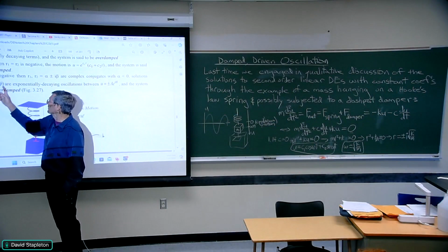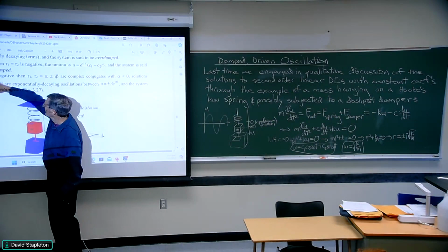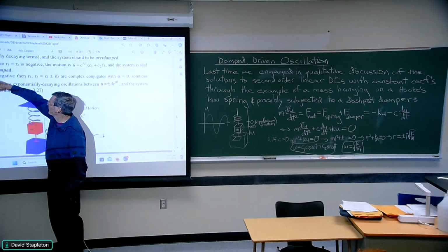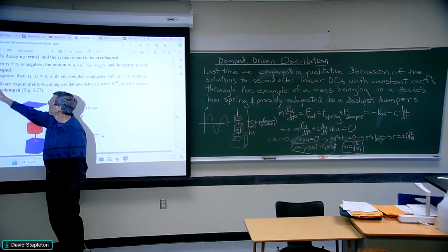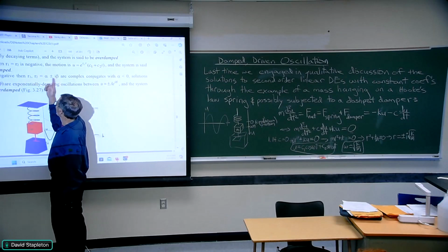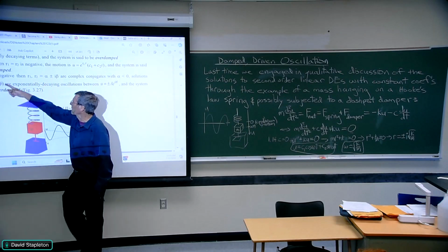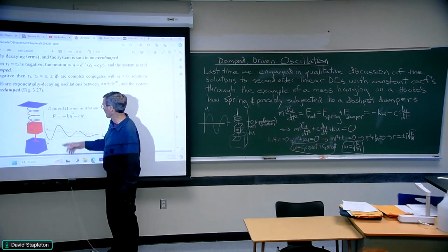And so it can be rewritten in this form, and you observe that it's a decaying exponential, because it turns out alpha has to be negative due to c, m and k all being positive. And then you get the constant beta out of the characteristic equation. It's got 2 complex conjugate solutions, which gives you this kind of solution, a sine wave times a decaying exponential.